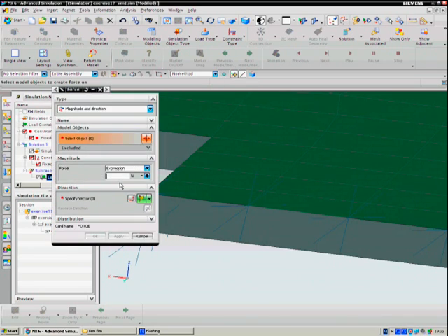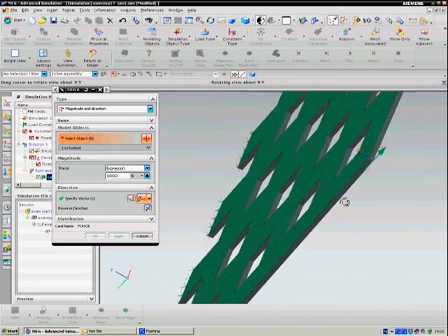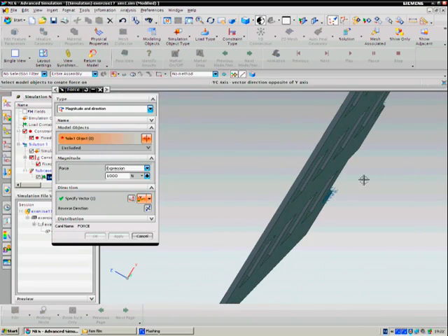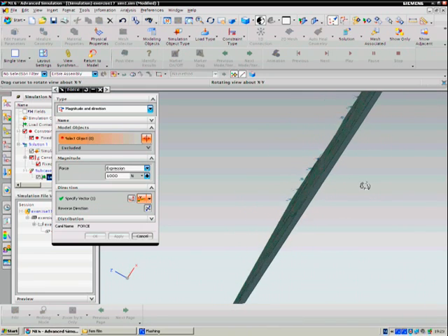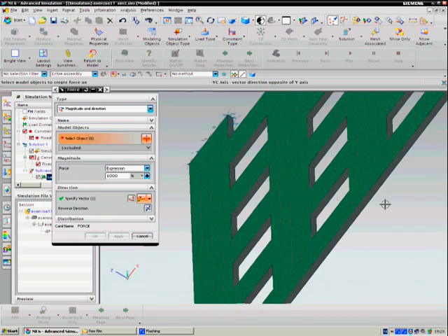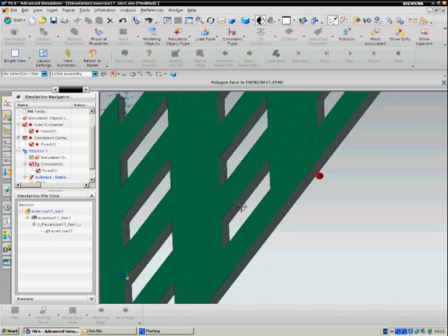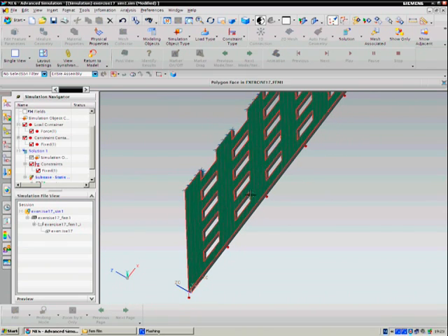Go to Load, New Load. We select the force. We also select the orientation of the force, and we select the edge where the force is applied. You still have to type in the size of the force and then yes, apply.